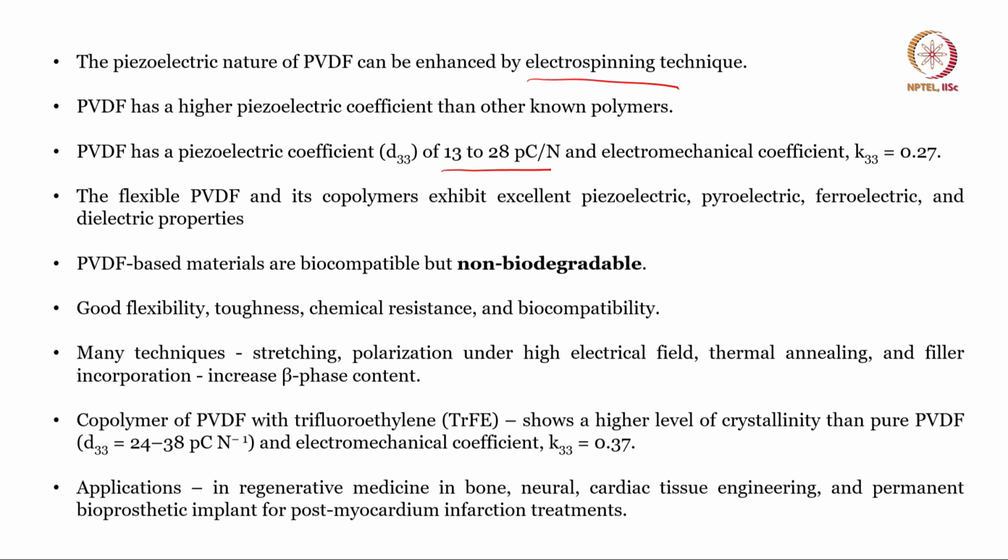The enhancement of piezoelectricity of PVDF can be brought about by using various techniques such as stretching of the material, polarization of the material under an electric field, thermal annealing as well as filler incorporation. Any of these techniques successively increases the beta phase content of the material and thereby increases piezoelectricity.